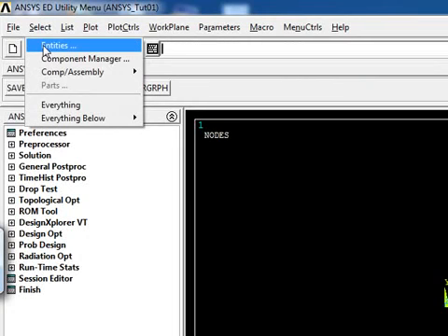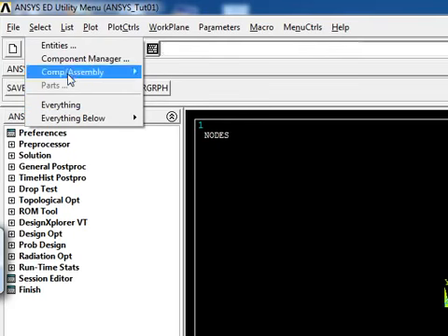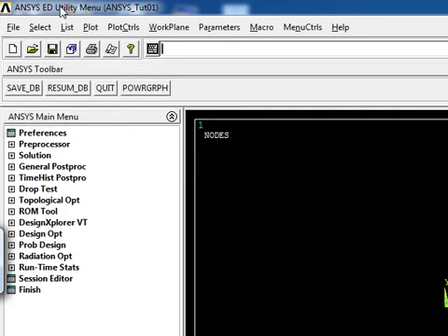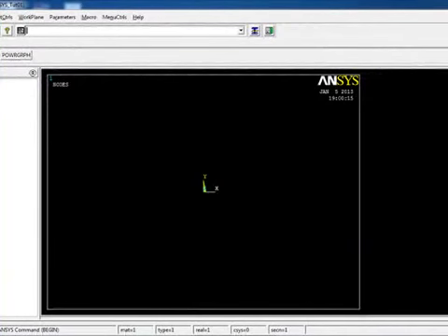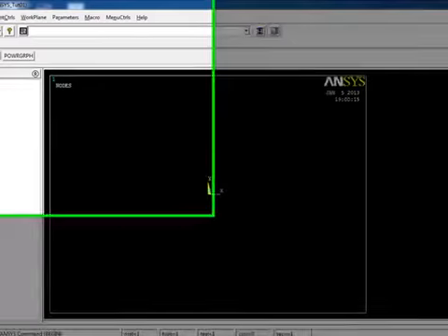Select is where you wanna, let's say, select just certain nodes or elements or lines or areas which are hard to click by mouse. If you have special criteria that you can distinguish those desired or required elements, then you can run these commands and select them, and then apply, let's say, loads or constraints in your selected line or element or area.